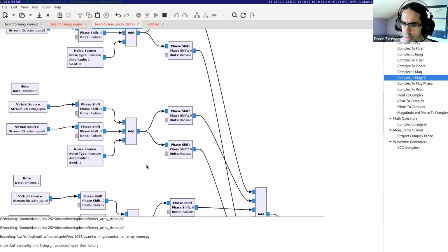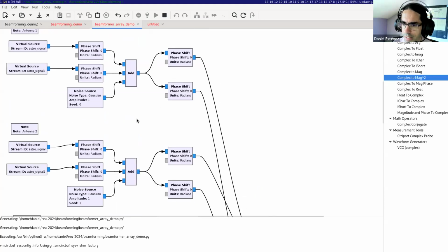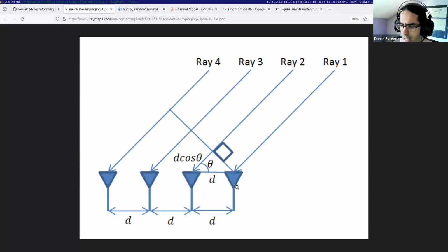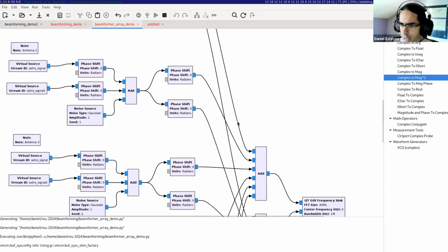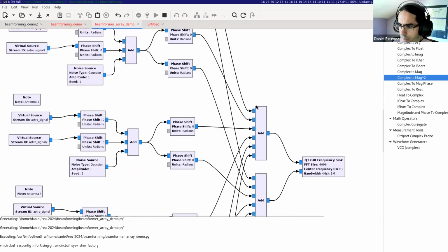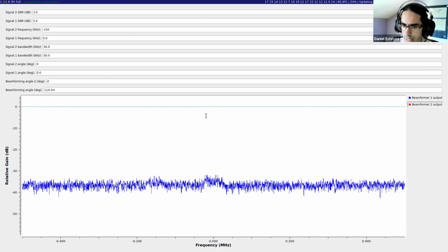And this looks very much like a Fourier transform. And in fact, it is a Fourier transform. So what happens behind the scenes, behind beamforming, is that the Fourier transform is always present because of how these phase delays act. In the case of a linear array, so that's what is nice about the linear array as an example, you really get a Fourier transform. So you really get a Fourier transform of, in this case, a 6-point Fourier transform of the angle, of the angular error.